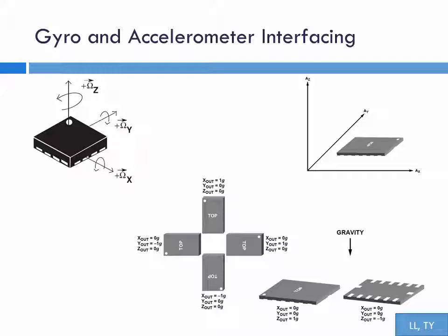In the case where axes are not parallel or perpendicular to the gravity, measurement readings show the axis projection onto the gravity vector. So if the x-axis, for example, were to deviate by 60 degrees from gravity, the reading would show 0.5g. For more information, please refer to the demo code on the Digilent website.